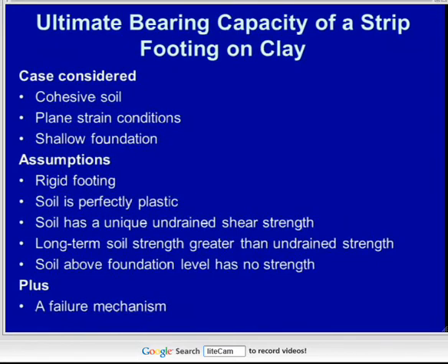In geotechnics, it's usually a safe assumption when you increase the stress on soil to assume that the drained strength is higher than the undrained strength. When you decrease the stress on the soil, it's the opposite way round. So when we load foundations, normally the undrained loading scenario is the more critical, because as we increase the stress, in time the soil will consolidate, get denser and get stronger.